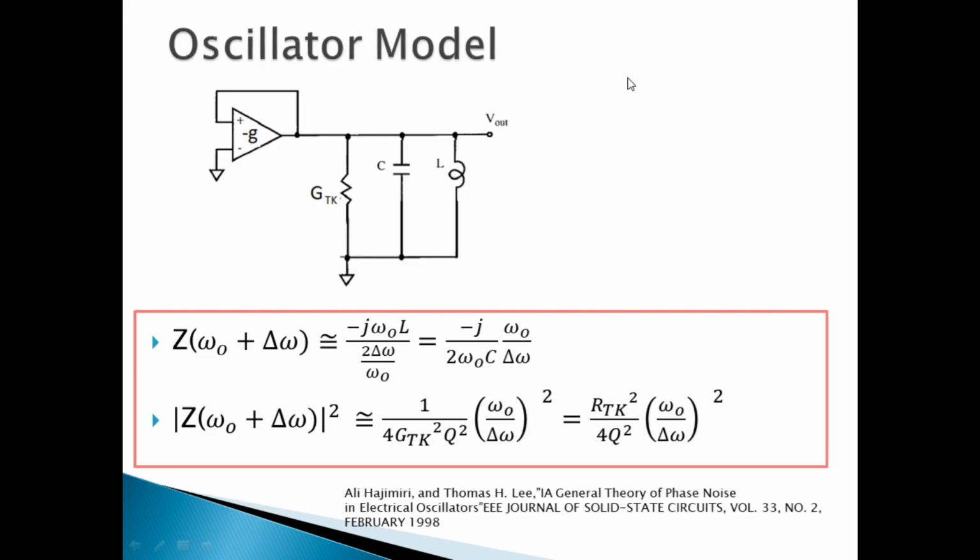So phase noise in essence is filtered noise, and it is filtered in a special way. Likewise, the noise contributed by the active part, the noise that takes shape in the form of a current, is filtered by the LC tank and converted into voltage that will be added to the oscillator signal itself.